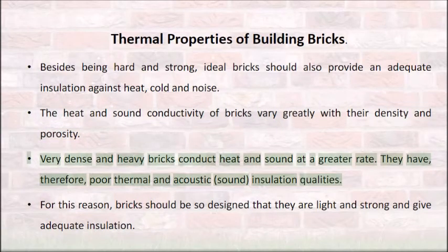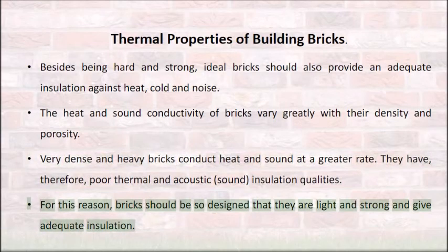Very dense and heavy bricks conduct heat and sound at a greater rate. They have, therefore, poor thermal and acoustic (sound) insulation qualities. For this reason, bricks should be so designed that they are light and strong and give adequate insulation.